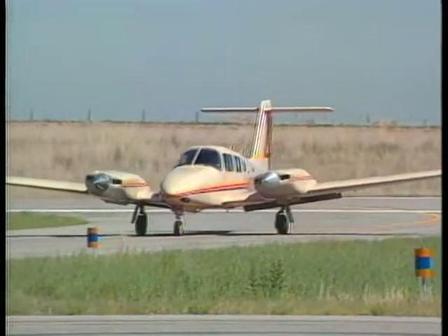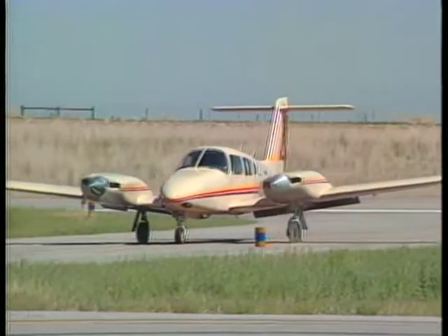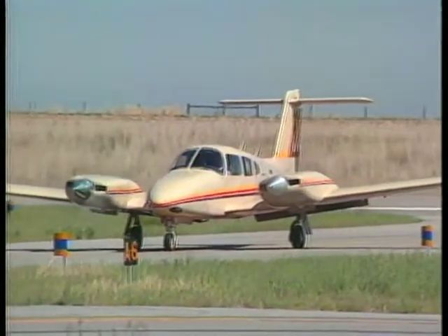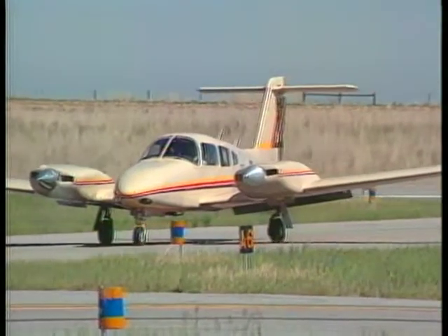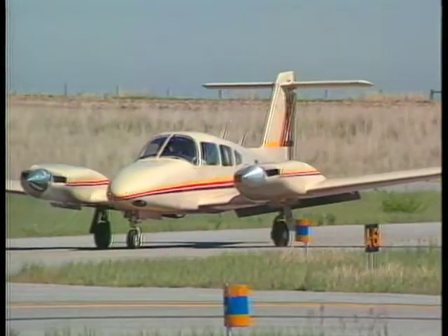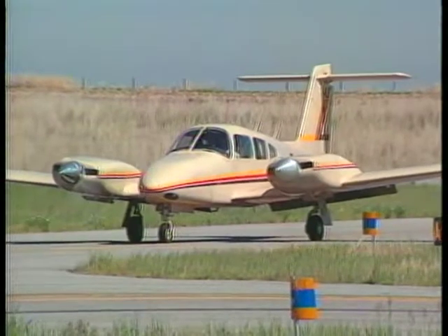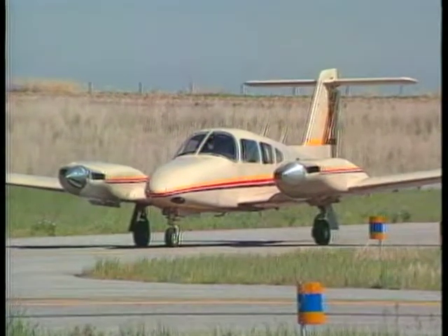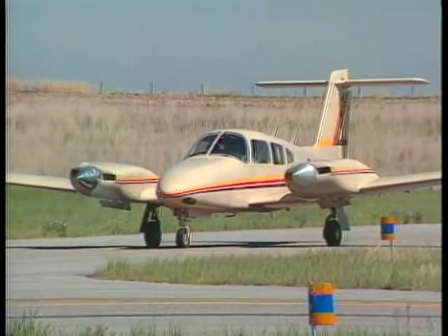However, if landing distance is not a factor, wait to accomplish the after-landing check until you're off the runway and can concentrate on activating the right controls. Raising the gear handle instead of the flap handle could be as expensive as it is embarrassing.